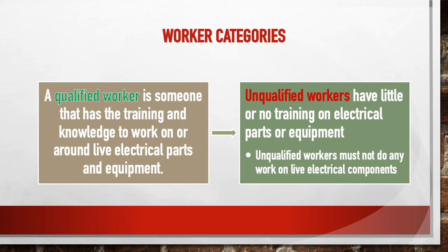Qualified electrical worker is someone who has training and knowledge to work on or around live electrical parts and equipment. Typically, they've attended NEC courses, have a journeyman's license. It's not just like, oh, yesterday I was unqualified and today I'm qualified because I took a test online. It's not like becoming a minister. There's actually some specific training that's required. And unqualified workers is pretty much everybody else, whoever has not received those trainings.